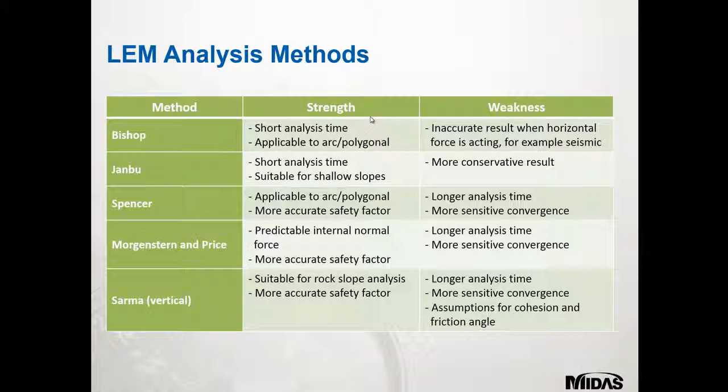As mentioned before, different types of LEM methods exist, differing in how they solve the problem of equilibrium of slices by statics. You can see the pros and cons of each method in the table. Bishop's method is most widely used for slope stability analysis and is well suited for clays, as cohesive materials often go through rotational failure of a mass volume about a point of rotation.